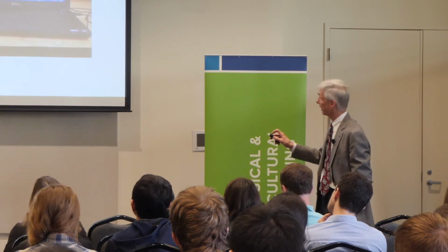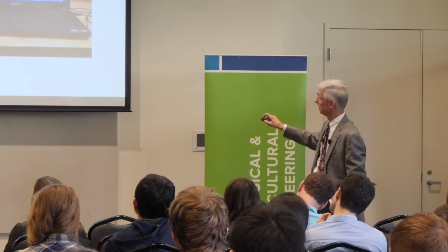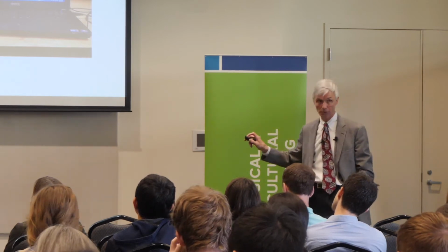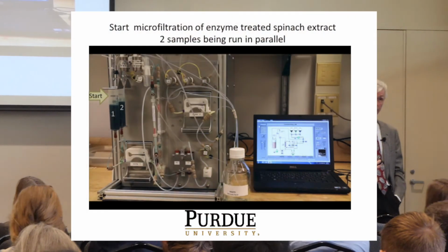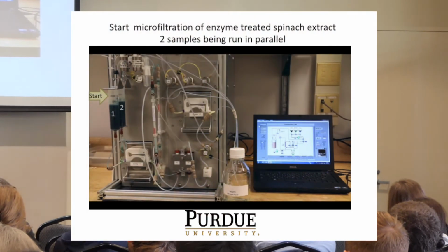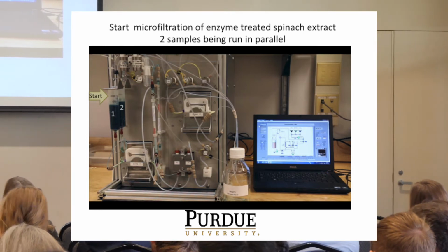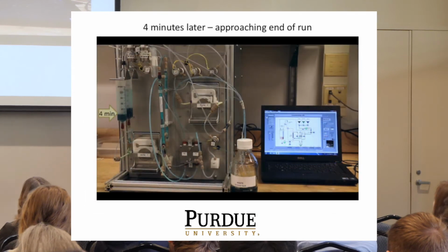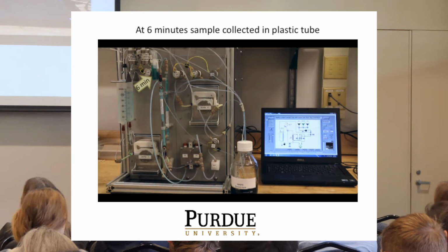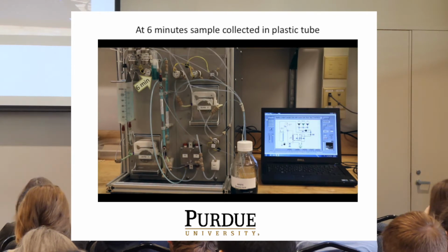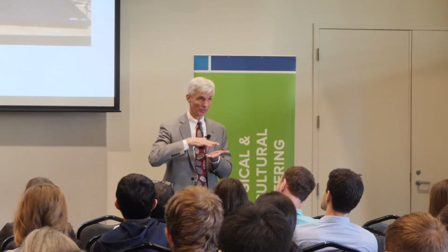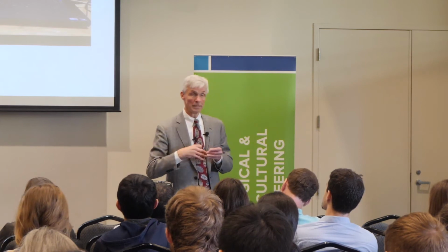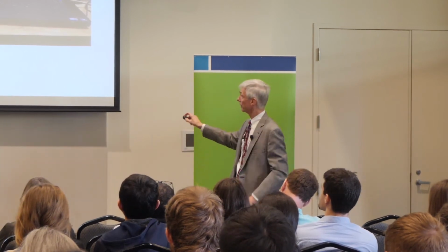And so here's an example. This is for spinach. We start with the fluid at 60 mils. This is a smaller sample size because we inoculated with a larger amount of microorganisms initially. And here's the waste reservoir. After 4 minutes, we've microfiltered about 45, 50 mils. You'll notice that they don't all filter at the same rate because the samples are a little bit different, the hollow fiber is a little bit different, and so there has to be some control so that you stop at the same point. Okay? But still in 4 minutes, you can see the fluid that's been collected.